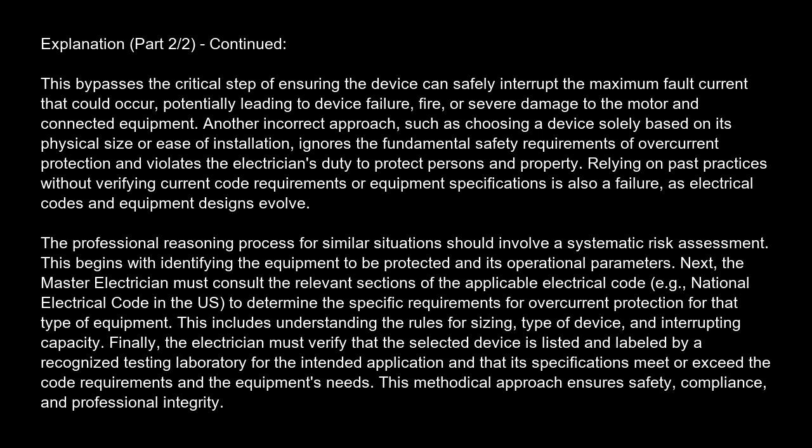Next, the master electrician must consult the relevant sections of the applicable electrical code, e.g., National Electrical Code in the U.S., to determine the specific requirements for overcurrent protection for that type of equipment. This includes understanding the rules for sizing, type of device, and interrupting capacity.